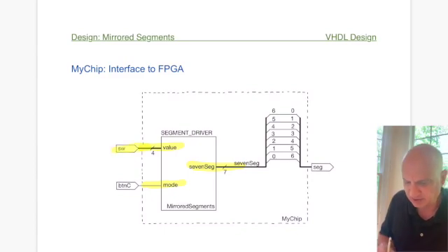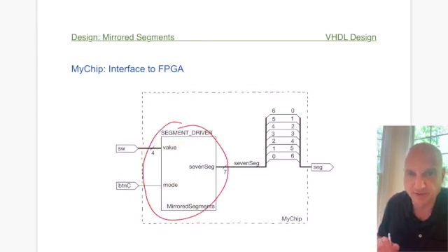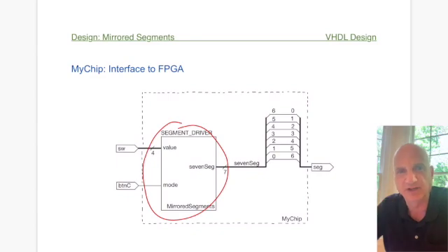You're going to make the lower 4 switches part of your configuration, the center button part of your configuration, and the segs part of your configuration. Once you've done that, you'll be creating this mychip.vhd file, which is a new component, and embedding inside of it the segment driver component we created in the other file. Because of the way the Basys board is made, it is different from the way we developed our segment code. In our segment code, we decided to start on the left with segment A, all the way to G as the far right bit. Basys did it the opposite: they made segment A bit 0, and segment G bit 6.